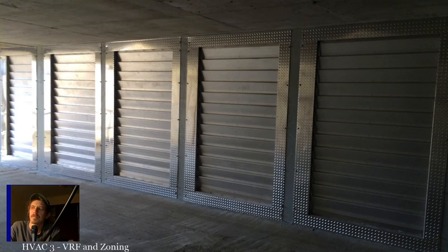And we talked about it last class, but I'll reiterate it here. If you're charging any of these systems, mini splits, VRF, newer systems with microchannel coils, I recommend you always charge systems by weight. It's imperative. You have no other choice on VRF or mini splits, really. If you're doing it properly, you have no choice but to weigh it in. But I'm telling you, as a rule of thumb, if you get good at always weighing in your charge, there's really no reason to fret too much about anything else.